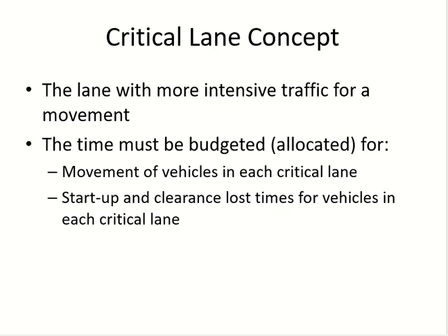Critical lane is which one? So you have, I am designing for this phase, and I have 3 lanes here. One of them can be critical lane. Why? I told you the reason. Because volume does not divide equally, and can be for different movements as well. So which one should be a critical one out of these 3? What is the criteria? The one which has higher volume, right? Most probably yes. In most of the cases, it is true.